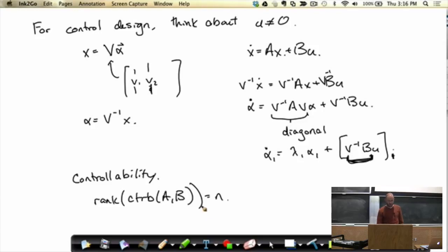But there's this notion of can I control every aspect of the dynamics with my linear system? And this is a classical linear systems thing, but we're not going to use too much, except to say I wanted to point it out since we had all the pictures up available in thinking about eigenmodal analysis. I wanted to bring this up because controllability asks the question: do I have enough control authority to drive the system to the origin from any initial condition? That's the question of controllability.